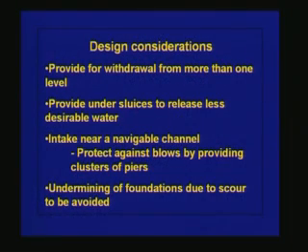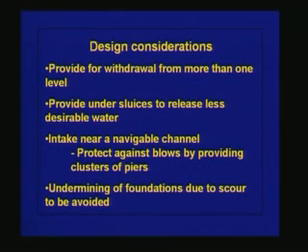First of all, we have to provide for withdrawal from more than one level. This is very important. In some of the intakes that I have shown earlier, we have multiple entries. This will help in proper operation of these intake structures during flow variation. Sometimes the water level in the source could be very high, sometimes it could be very low. That has to be taken into consideration, and that is why we provide for withdrawal from more than one level.